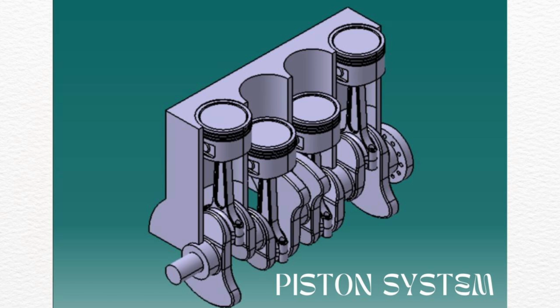Several forces act on the piston, mainly gas pressure, friction, and inertia. As the crankshaft turns, the piston position, speed, and acceleration constantly change, creating a complex motion. These changes affect how much force is transmitted and can cause vibration if not balanced properly.